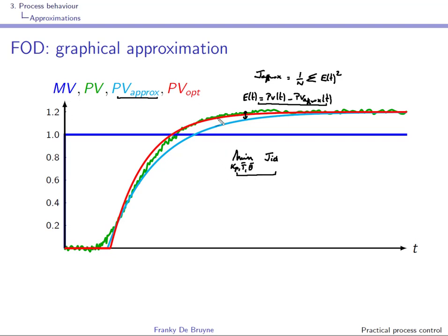And this will try to minimize the discrepancy between what comes out of the model and what comes out of the experiment, right? And you can implement such an optimization using, for instance, fminsearch, a MATLAB function. And this is something that you have done in the laboratory associated to fundamentals of control theory.